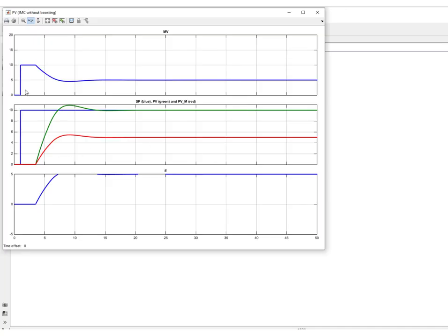This is what you see over here, and of course we have accelerated the response, right? So this can be done in this step 2 IMC controller to improve the time constants of the system in closed loop, so decrease the time constants in closed loop. But clearly we would like to have a mechanism that allows you to put the actual gain in the faceplate and have another mechanism to boost the closed loop response, and this is what we'll do in the step 3 IMC controller.